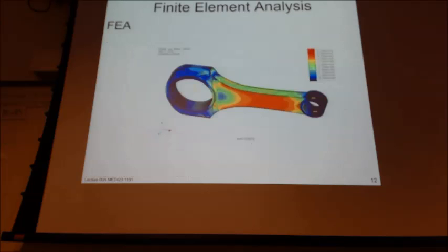So some of the key assumptions that we're making when we deal with FEA analysis, we have 4 primary assumptions that we're going to deal with: geometry, properties, mesh, and boundary conditions. Okay, so the CAD geometry is a template for our mesh, and as I said before, the FEA solver doesn't understand the geometry. It's looking at the nodes and the elements. So we have to make sure that our mesh adequately represents the geometry. And we're saying that it does when we're doing our analysis.